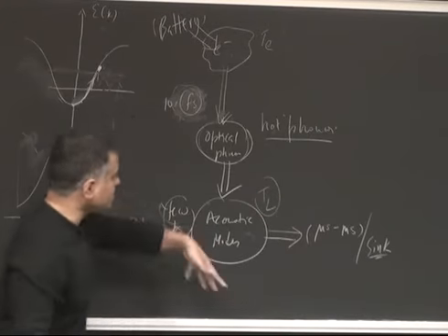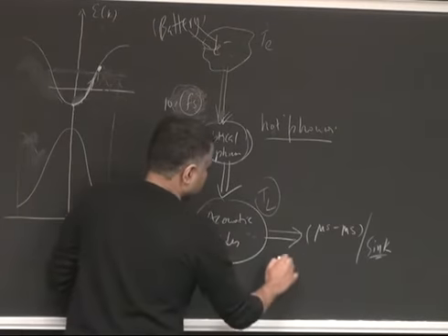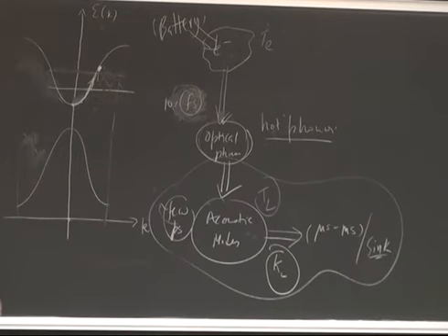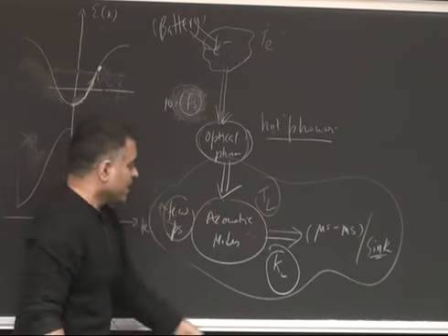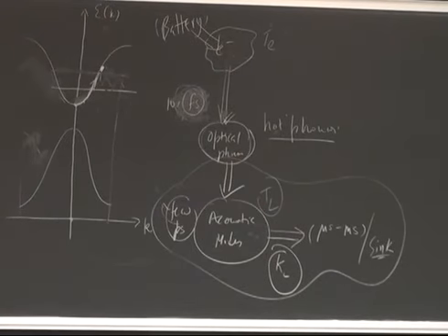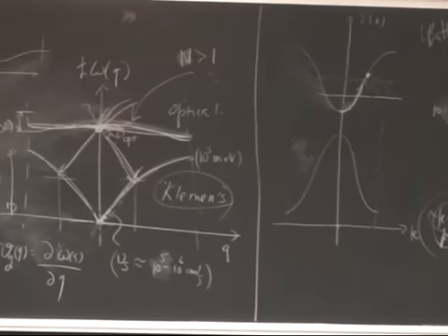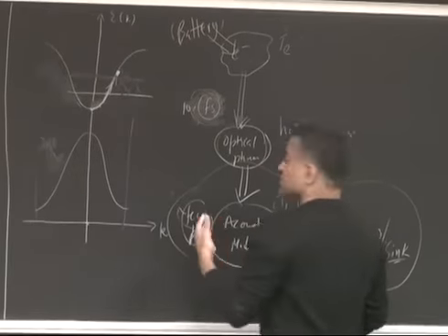So, okay, that's a detailed picture of what happens in the microscopic range. But essentially, the thermal conductivity is the business that happens in this window. It's not in the upper window. After all the energy has entered the acoustic modes, that's where the thermal conductivity comes in. Thermal conductivity is dominated by acoustic phonons, and optical phonons have a small role to play. I will explain what I mean by that. Is that clear? I just glossed over it, but it's important to know the time scales and where there can be bottlenecks.